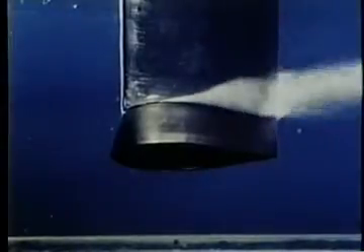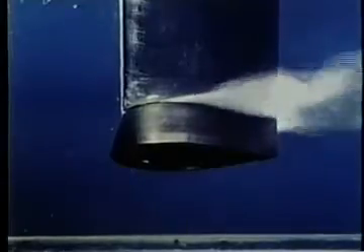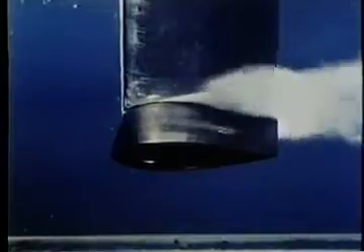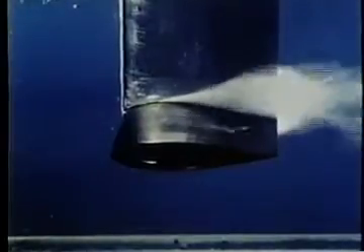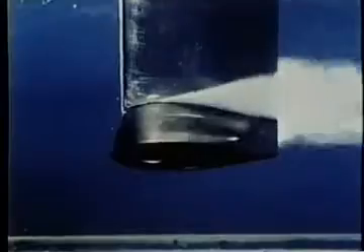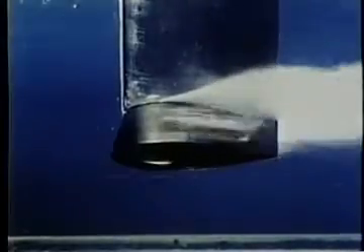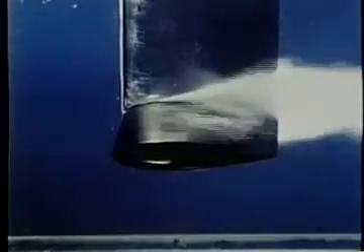Let's turn now to an examination of some of the effects associated with cavitation and cavitating flows. What happens to a machine when it begins to cavitate, and how does performance vary with increasing extent of cavitation? Since hydrofoil sections make up so many different types of machines, pumps, turbines, propellers, propeller shaft struts, mixers, we can illustrate what happens to all such machines by studying the forces on the hydrofoil section itself.